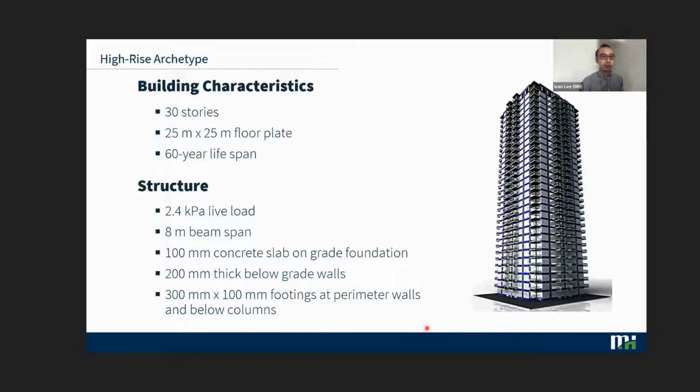So some of the characteristics, at least for the high-rise: we set it to 30 stories, with a floor plate of 25 meters by 25 meters, so it's fairly compact. The lifespan is around 60 years, similar to most LCAs. As far as the structure, we set the live load at 2.4 kPa and an 8 meter beam span, and this is really more for Athena than anything else.